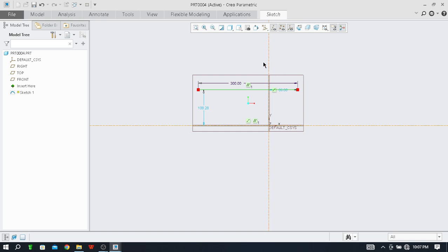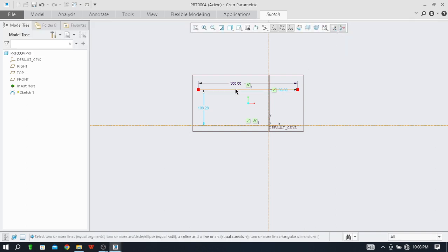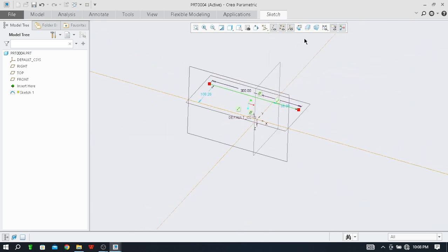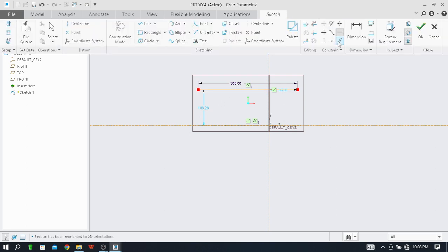Okay, the system actually didn't generate it. We'll again perform this equal. Click on the first, then the center, and then this point. I don't understand why the system has not created this equal, because I have already used this one constraint, parallel, over there.